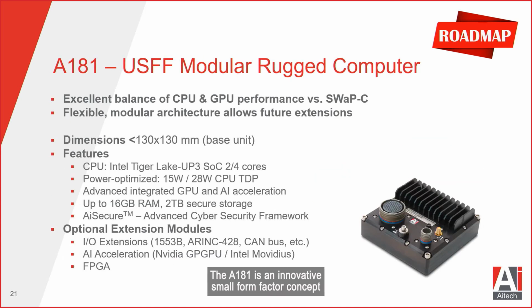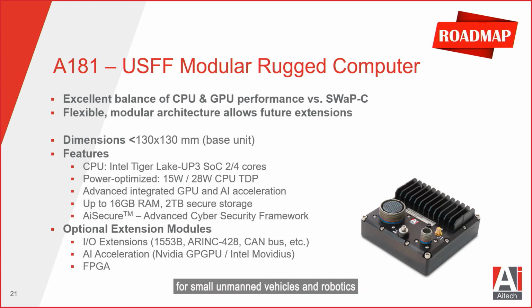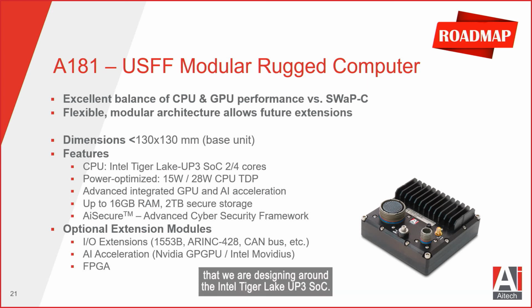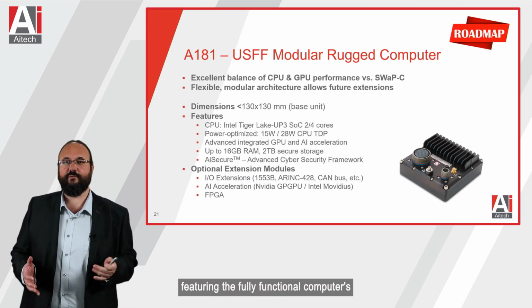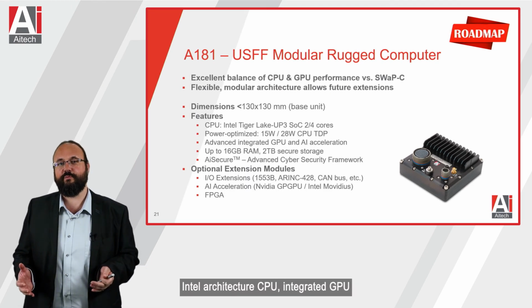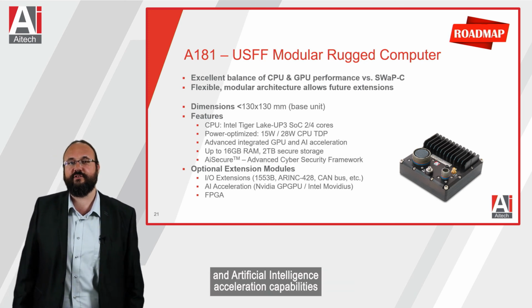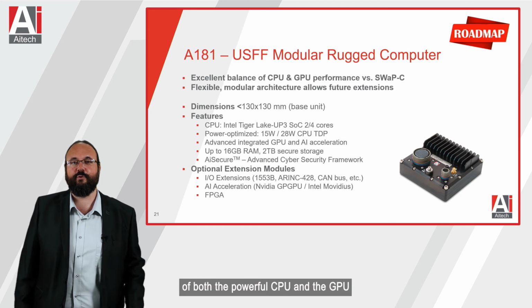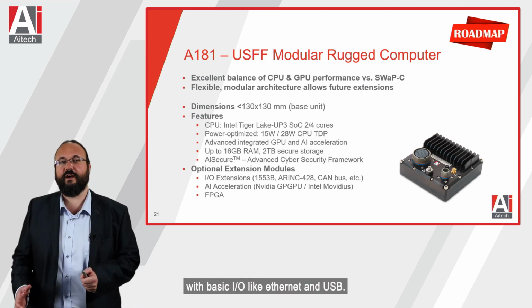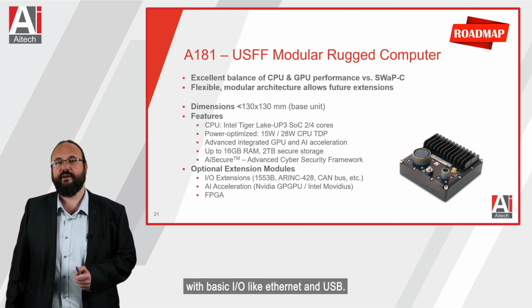The A181 is an innovative small form factor concept for small unmanned vehicles and robotics that we are designing around the Intel Tiger Lake UP3 SoC. It's a modular rugged mini computer. It will be available as a standalone miniature base unit featuring a fully functional computer with Intel architecture CPU, integrated GPU and artificial intelligence acceleration capabilities. This provides a balanced combination of both the powerful CPU and the GPU with basic I/O like Ethernet and USB.